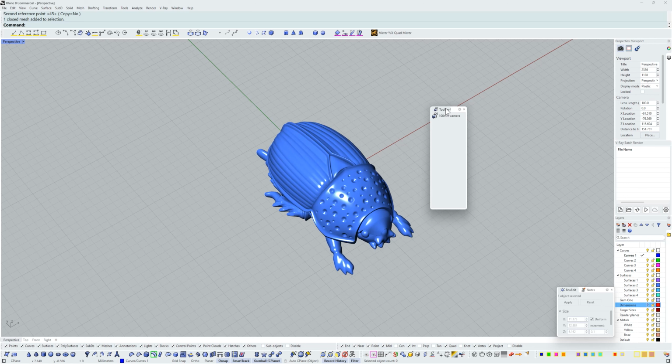Now in previous videos, I've created some macros. I've got a mirror y/x. I'm going to hold down Control and copy this into my new toolbar, and the same with my quad mirror. I'm going to copy this here. Now with my first button, I don't actually want this. I'm going to hold down Shift and left click and drag this out, which is going to delete this toolbar item. So that's our toolbar.